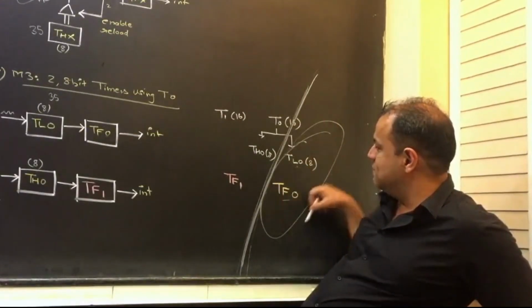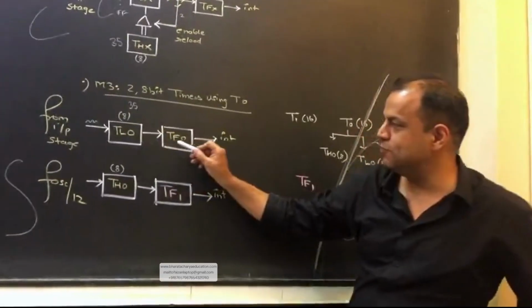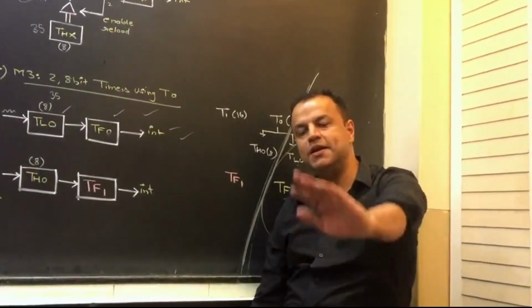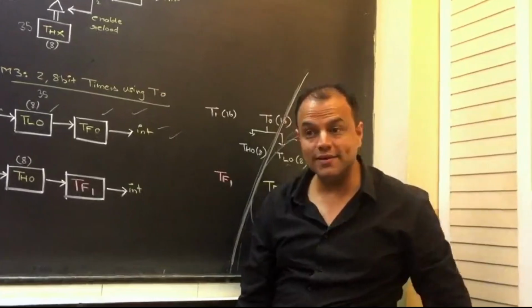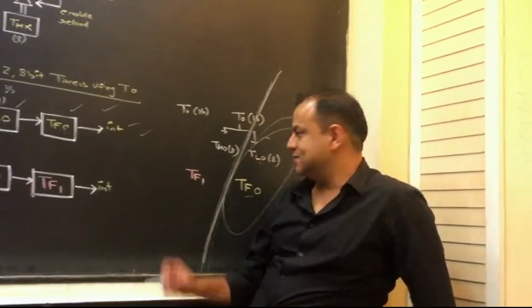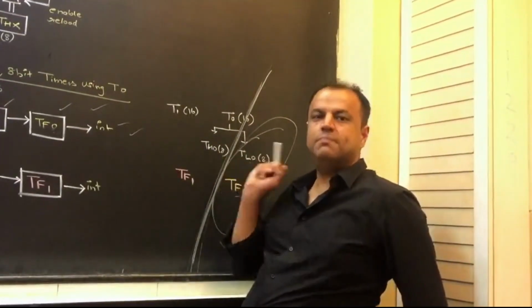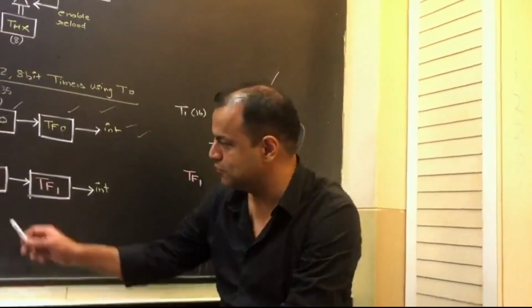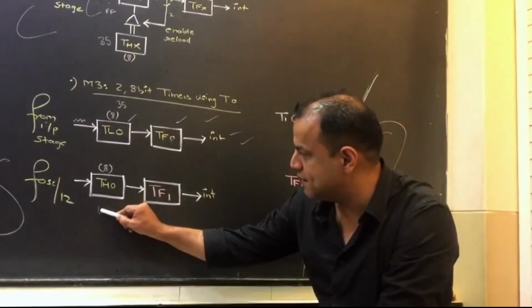Don't come to me. This has become my flag. So timer 0 lower byte uses the overflow flag of timer 0 and has successfully become an 8-bit independent timer. Now who wakes up? Timer 0 higher byte. It says, just like this one has been made an 8-bit timer, make me also an 8-bit timer. I mean, I want to work like an 8-bit timer, no problem. We'll do that also. Timer 0 higher byte, we give it a count like 40.